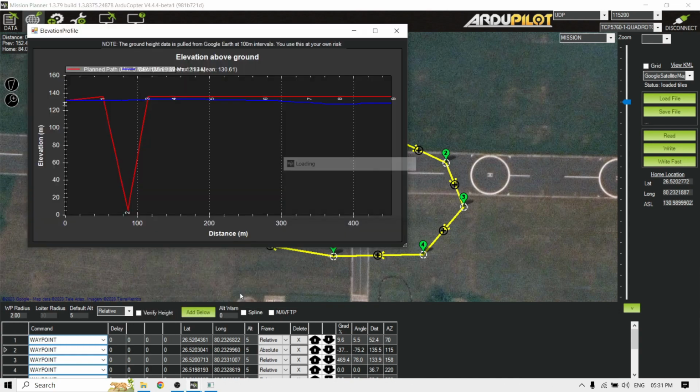Then here, elevation graph. If you check over here, if by chance the blue and red lines are meeting or intersecting, then it just means that our drone has crashed to the ground. Basically, if there's an intersection, it just means that from the ground position we are taking off. Pretty good. And as soon as we reach the second waypoint, reaching to the mean sea level 5 meters. So this is 0, this is C, and from here 5 meters, and here is our ground. We are crashing, and these other things won't happen.